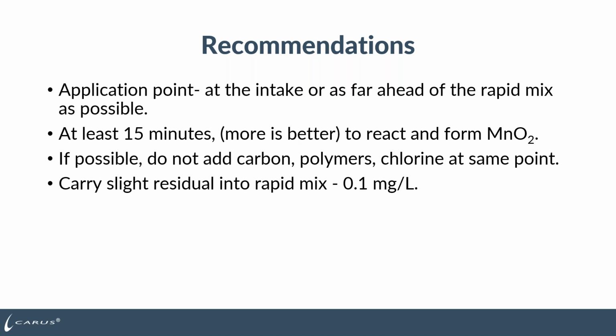Coagulants like aluminum sulfate, polyaluminum chloride typically are non-reactive with permanganate, so they don't have a demand. But if you are feeding a copolymer, it's something to check in the jar test to see if that polymer is oxidant resistant. Sometimes polymers will react with permanganate and you won't get good coagulation. So it's definitely something you want to try in the jar.